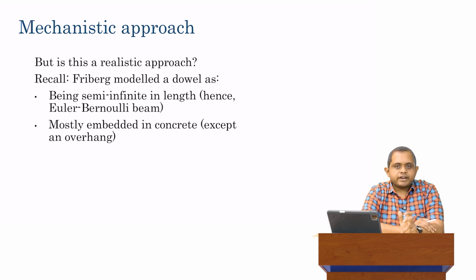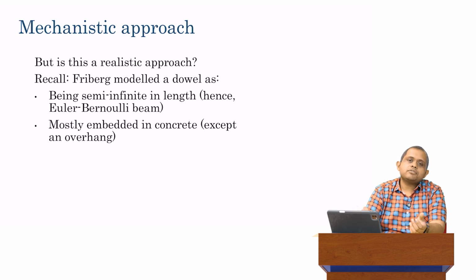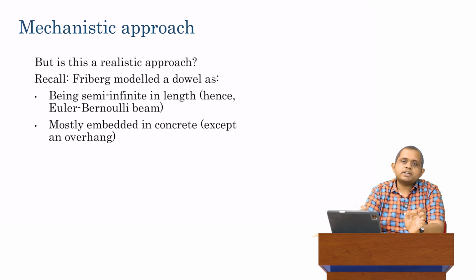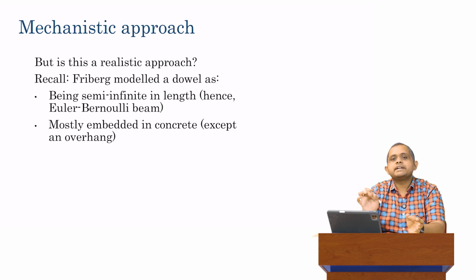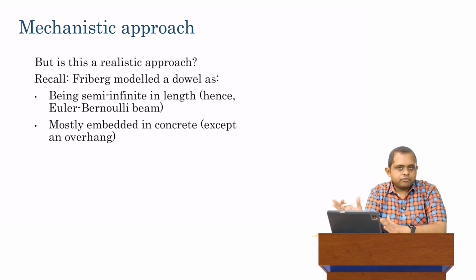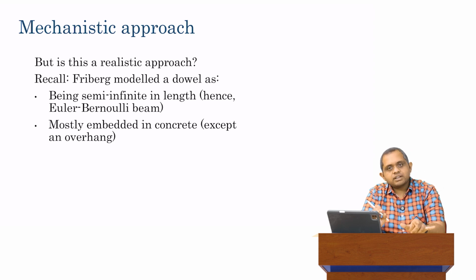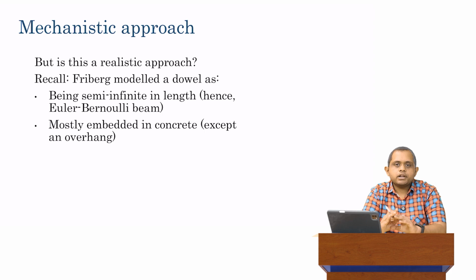Now, this is fine. So what we've successfully done is we started first by assuming that the joint is an interaction between the vertical degrees of freedom, or the displacement degrees of freedom. We modified that, and that came from some spring stiffness. We modified that to say that the joint is actually an interaction between the rotation as well as the displacement degrees of freedom across the joint, and the physics of that interaction we modeled using an Euler-Bernoulli beam. Okay, straightforward.